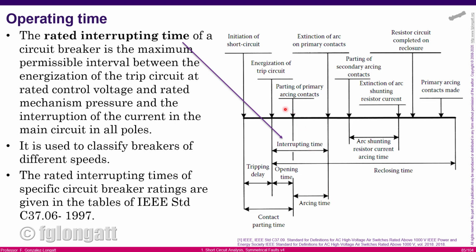What I'm trying to say is there is a short circuit, then the relays and other devices take time, send the signal, and the breaker starts to open the contacts. That is not instantaneous. But at the moment that the contacts open, there is an arc, and that arc gets longer and longer, and finally we reach the point that the arc is stopped, the fault current is stopped, and that is the operating time.